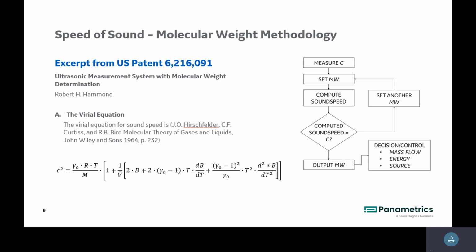And then, of course, it's an iterative process or regression. So basically, you have a sound speed, you guess a molecular weight, and then calculate the sound speed. If it matches, good; if not, change your molecular weight and calculate again, until it converges. That's how you calculate the molecular weight from sound speed, and that's the key methodology for all of this. It's based on this method.